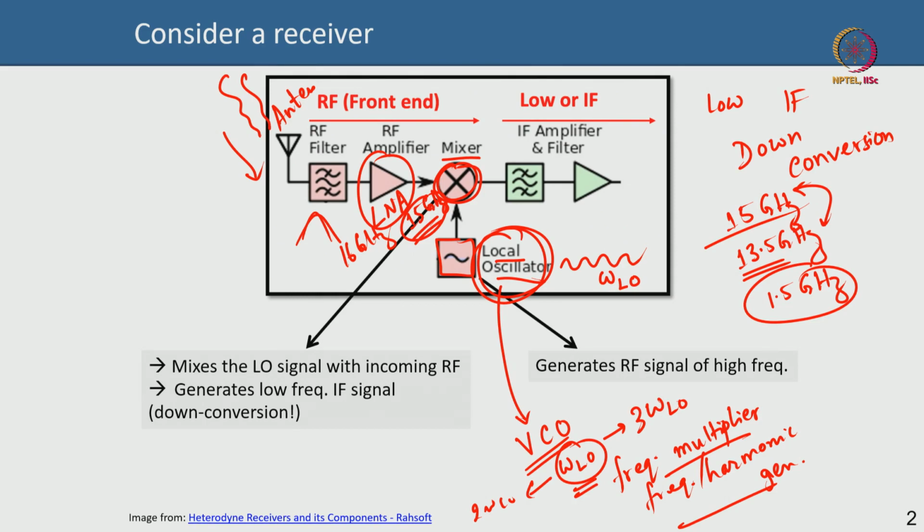Okay. You are getting from omega, 2 omega or 3 omega or 5 omega depending on what kind of frequencies you want: doubler, tripler, quadrupler, quintupler, etc. Okay. So that is a frequency multiplier that is very important, and remember that the frequency multiplier is not the only component in the local oscillator. You have an entire circuit and there are many oscillator circuits, but this frequency multiplier could be necessary in many applications where you want to increase the frequency to multiple harmonics of the original frequency that the local oscillator is generating.